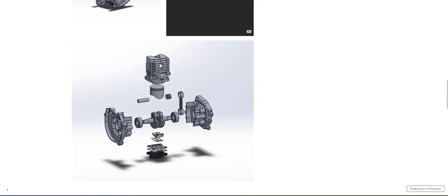All the parts are going to be done by sand casting. This will be done by die casting. This will be machined from a bar. This is a bearing. This will be casted, forged, and machined; bearings are an off-the-shelf item. This can be done by the die casting process or the forge casting process. Then we're going to have the trimming for the side, then machining from the inside.